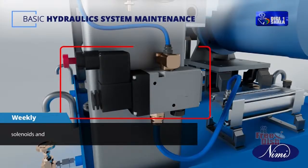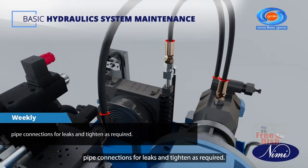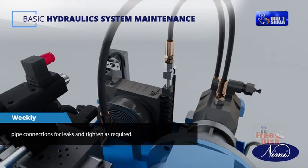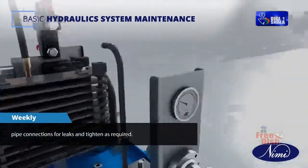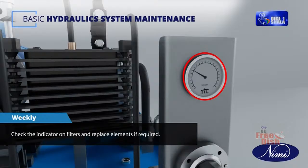Check solenoids and pipe connections for leaks and tighten as required. Check the indicator on filters and replace elements if required.